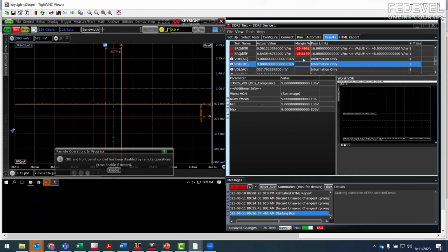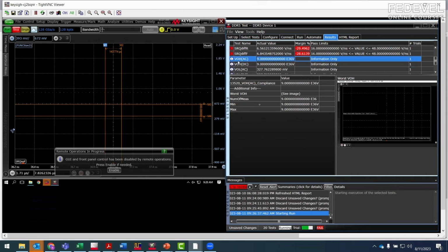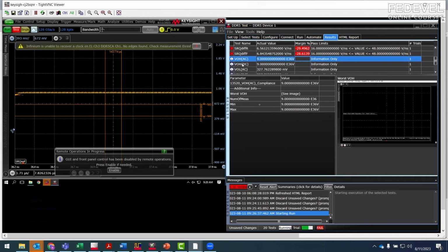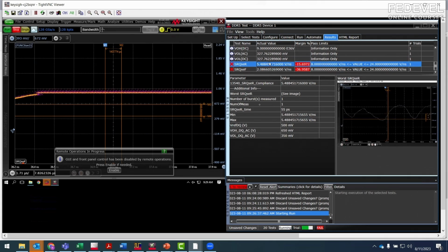And so we would need to go back and look at why the B output high, why that did not capture the signal right. Well, I'd say in my experience, 80-90% of the time, it's because of the threshold setting that I used in the setup. I would need to fine tune that a little bit more. But anyway, we've got some more results here.